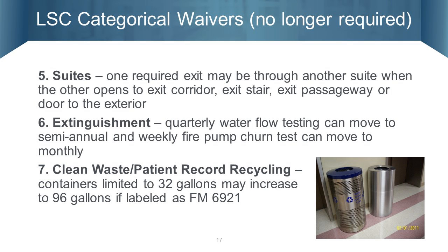Now as a suite, you only require 1 direct exit to an egress corridor. The other exit can be through the adjoining suite. For many organizations, for their ORs as well as the ERs, that has allowed them to call them suites now and gain the benefit of it being a suite where you don't have egress corridors that must be kept clear